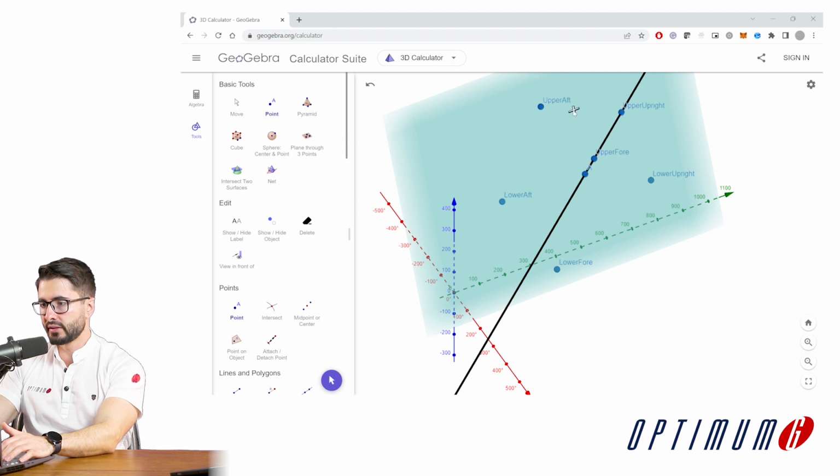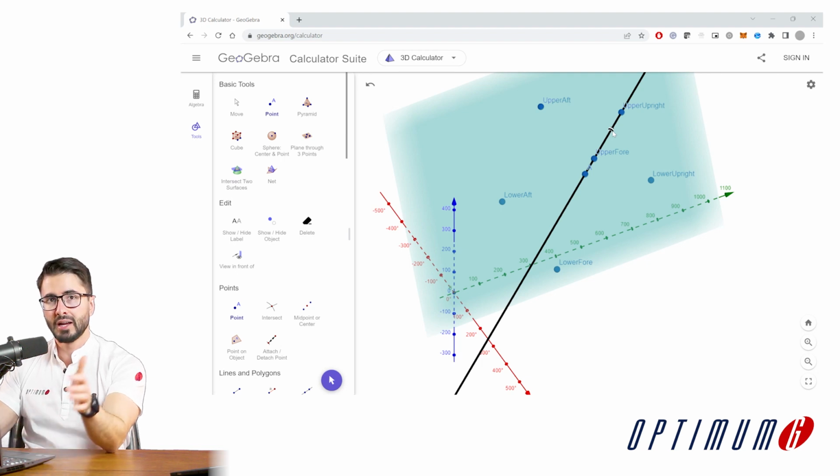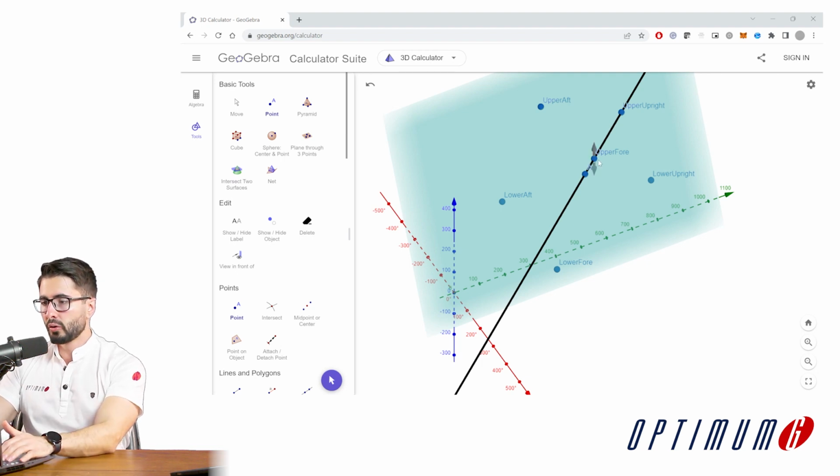Besides that, we also notice that these wishbones are pretty short, so we can use this opportunity to make them a little longer and possibly make the chassis a little narrower. So we can do that for all of the pickup points in order to adjust the Y coordinates and the X coordinates as required. And with that, we are going to find our new V6 after we implement the changes from the feedback.